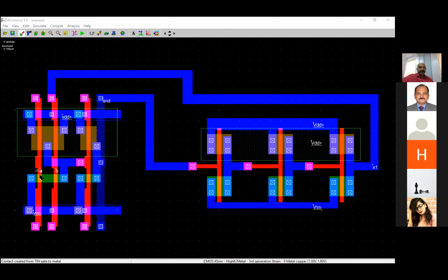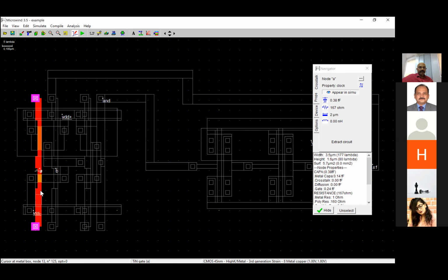Now I will verify that my system is well connected and there are no errors. I double click on the gate input of A, the red body of the AND gate. It should highlight only A and de-highlight the entire rest of the circuit. Is it doing the same at your place? Yes, sir. Okay. Now only left click once on the B input.